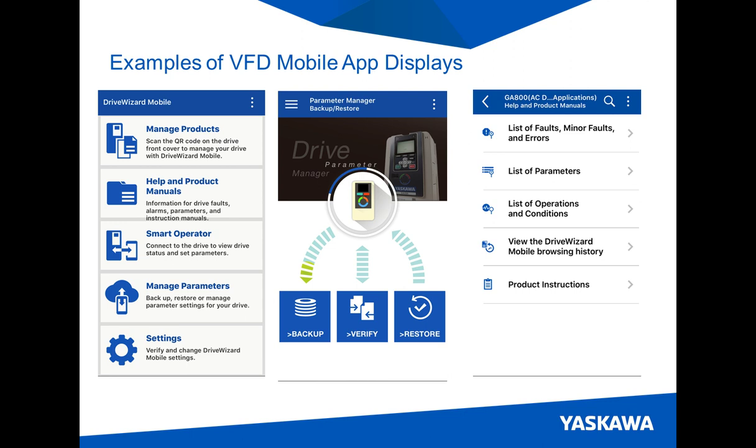So the touchscreen versus directional arrows, you can get more information on the display. It's intuitive, we're familiar with it, and it may be easier to learn. And we can have features in there that don't lend themselves to be designed into an HMI interface on a VFD. Wireless access, again, I'll hit on that. It can improve accessibility and safety when working in or around the VFD.